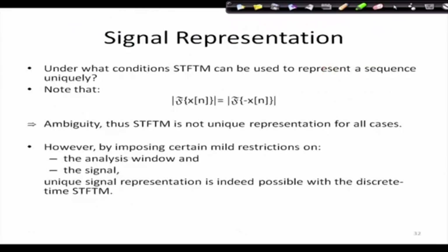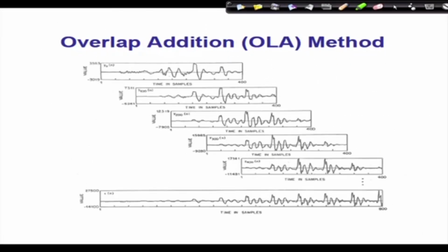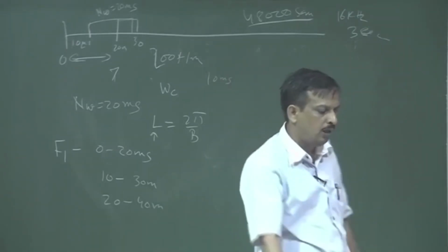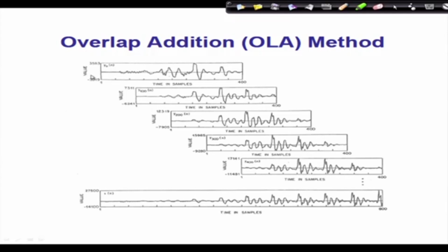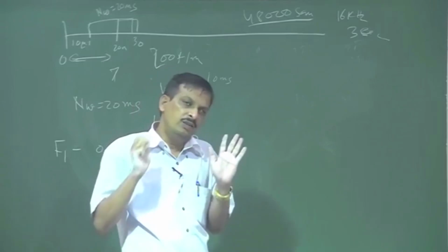If you see, there is a picture I have shown you, you can go through this slide also. So I take frame by frame, I can make 75% overlap also. I analyze the frame, and with the inverse Fourier transform I get back the frame. Then I add all those frames, I get back the signal. Okay. So this is the overall STFT analysis.